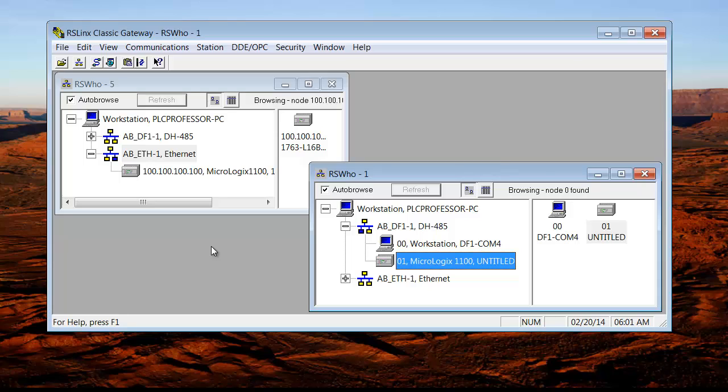Now, why would we do this? We wouldn't. However, you definitely can use both ports on the PLC: one to an HMI, a screen, a monitor, an operator interface terminal, and the other to plug into your laptop. The nice thing about the 1100 is that it supports Ethernet. And Ethernet is very easy to deal with if you know what the IP address is in the controller. For the 1100, it's very simply a matter, as we demonstrated, of configuring an RSLinx RS-232 driver, going into the controller, looking to see what the configuration is for the Ethernet port, unchecking BootP if it's checked, typing in an IP address, making it fixed, and then going to your laptop and changing the Ethernet port on your laptop to be in the same subnetwork, and you're all set.